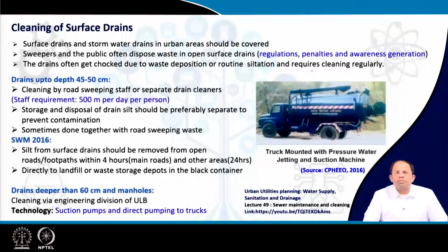Now, coming to cleaning of surface drains, of course, surface drains in urban areas should be covered, and the rest, of course, there should be a sewerage network. But in many cases, surface drains in our country are not covered, because of deposition of silt or the normal deposition. Even though surface drains should be designed so that they have adequate self-cleansing velocity, they should be clean, but still siltation happens and it needs to be cleaned at certain intervals.